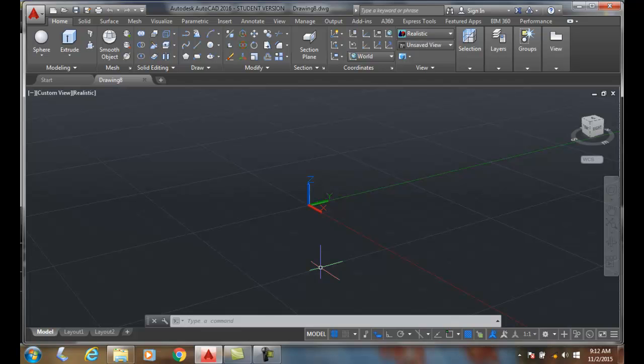Creating a helix. A helix is a spline that really forms a spiral, and it could be a 2D or 3D object. These spirals work really good for making things like springs or spiral staircases. Now, it's really not a 3D object, but we can use this to create a 3D object. We can find the helix located up here in the draw command.